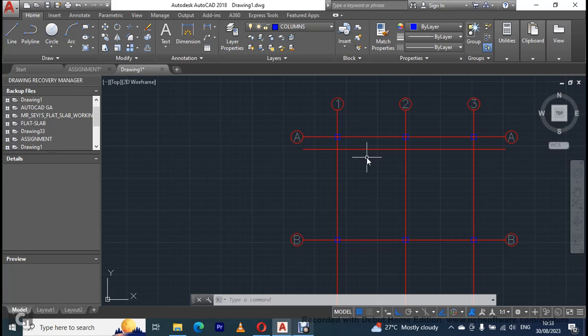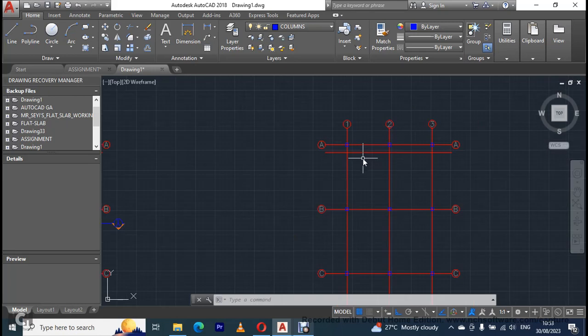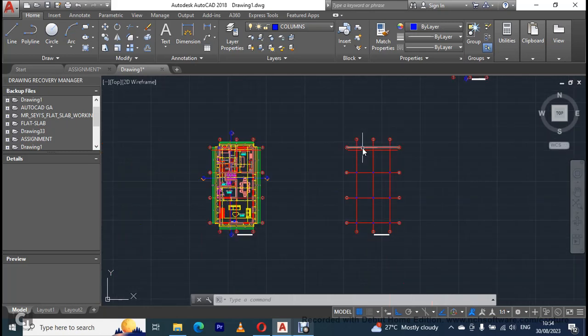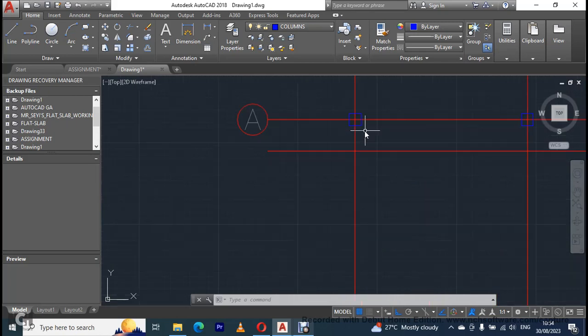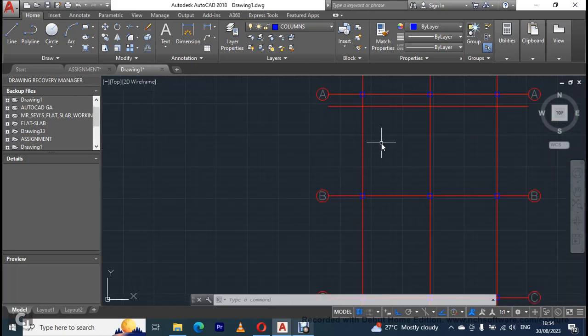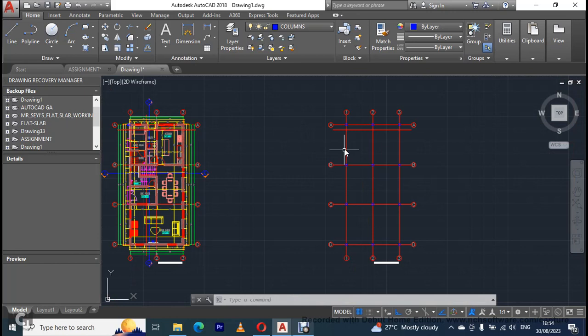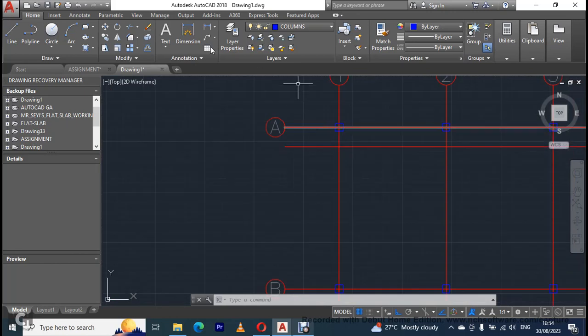And there are other types of slabs we have. Again, we have rib slabs and waffle slabs, in which a portion of the concrete in the tension zone is reduced, in order to reduce the self weight of the slab itself. So for this video I'm going to be working with a solid slab, so that means we have to place in our beam members.